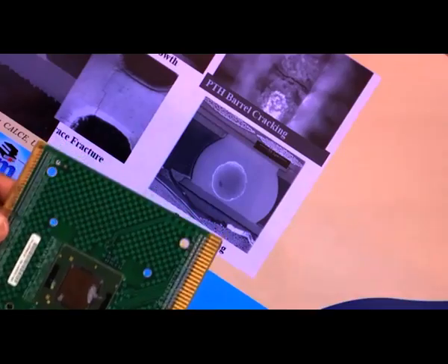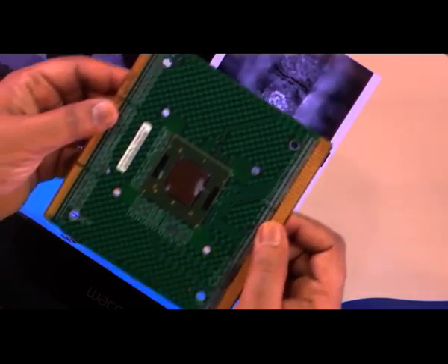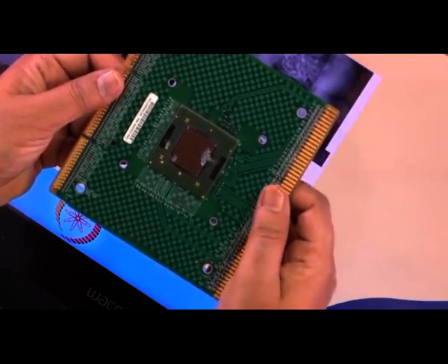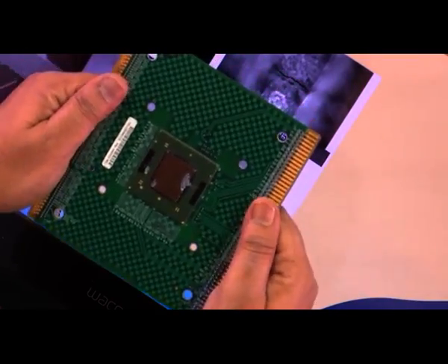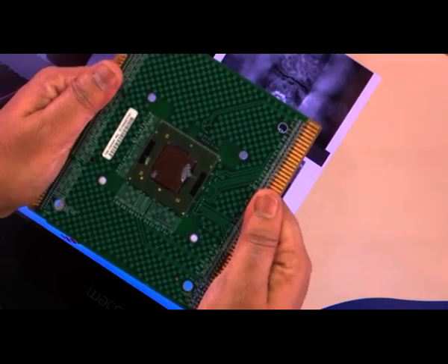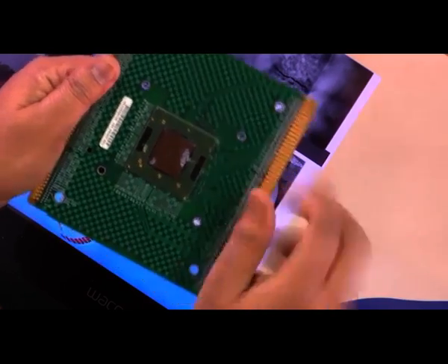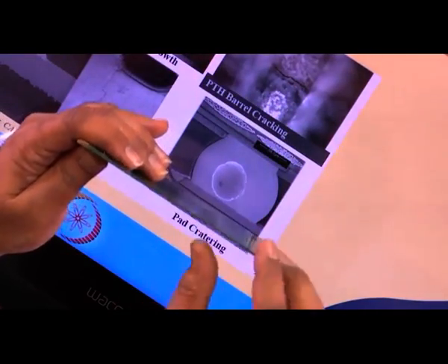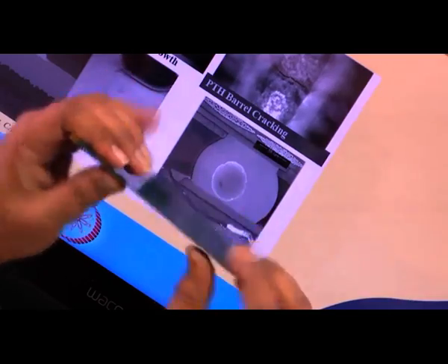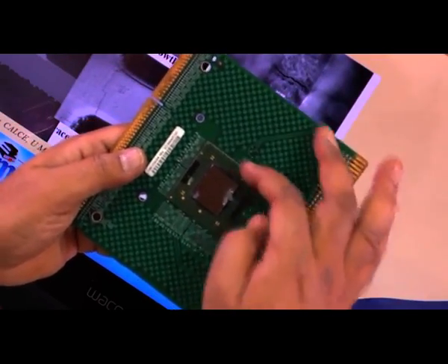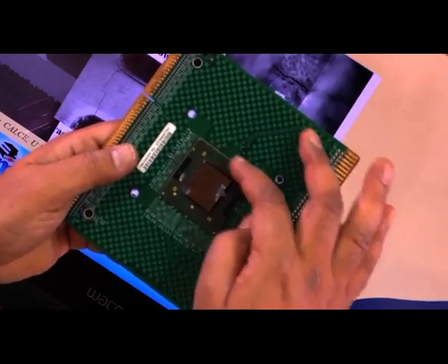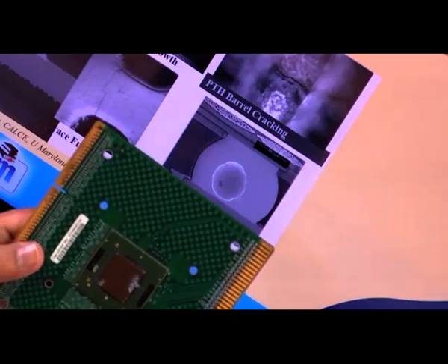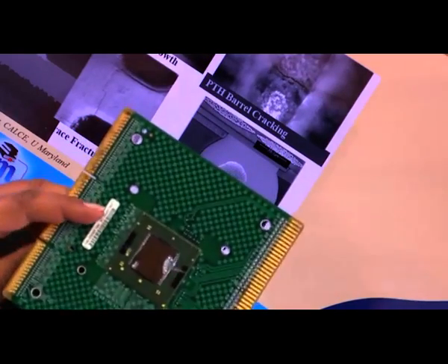Now, I heat it up. Okay. If I heat it up, then what happens is the silicon is going to expand to a certain level, the motherboard much more. So, now because this is held at the two ends, what will happen? In order to expand, it has to warp. It is no longer a straight line like this, but it will be bent like this. Okay. And this warpage, therefore, what will happen is from the end the connections may kind of open up. All right. So, this is important.